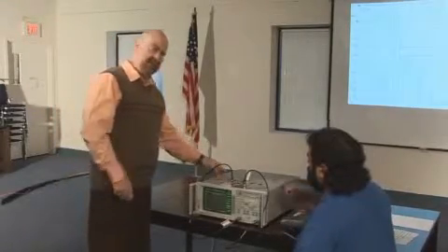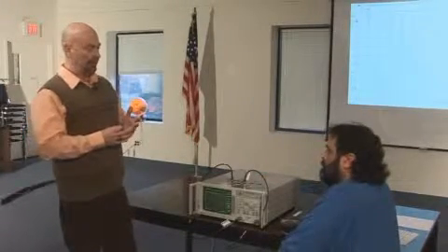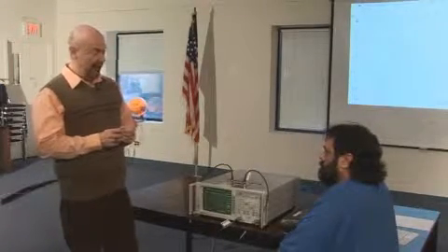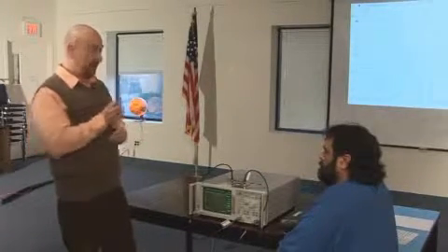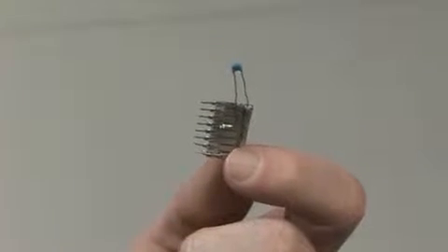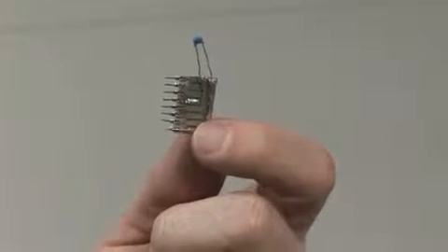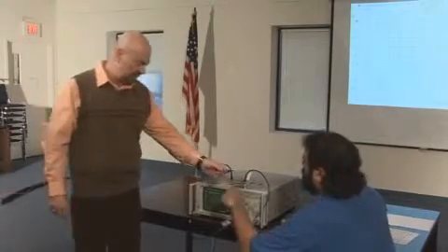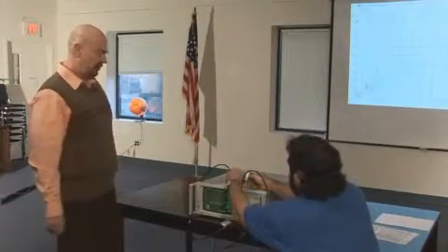One of the problems I see typically in the lab is that a lot of times customers, people with problems, will have 1 or 2 problem frequencies they can't get rid of. And they'll go for passive components. There's all kinds of passive components, but the most common ones that people use are capacitors. And unfortunately, they'll open a bag up or go to a bin, and they'll grab one of these ugly-looking things here. See that I have a capacitor here. Has about 1 inch to 1.5 inches worth of lead on it. What they'll do is they'll start tacking these. If you'd be so kind to put that in, we'll see what kind of effect this has on our transfer characteristics.